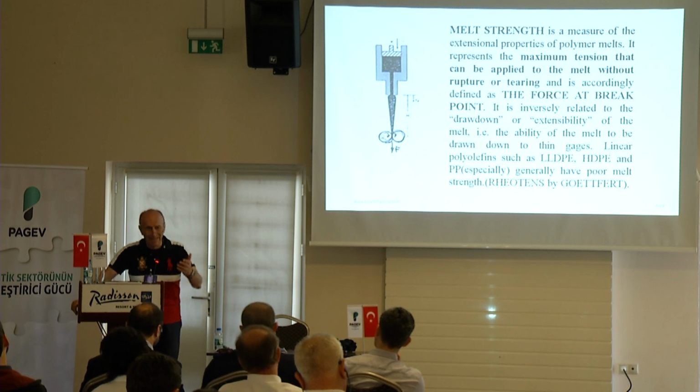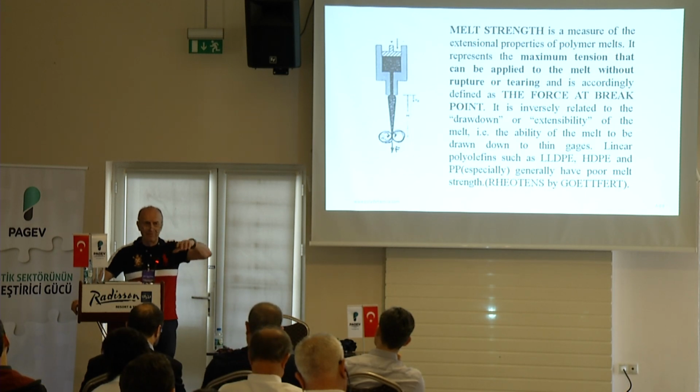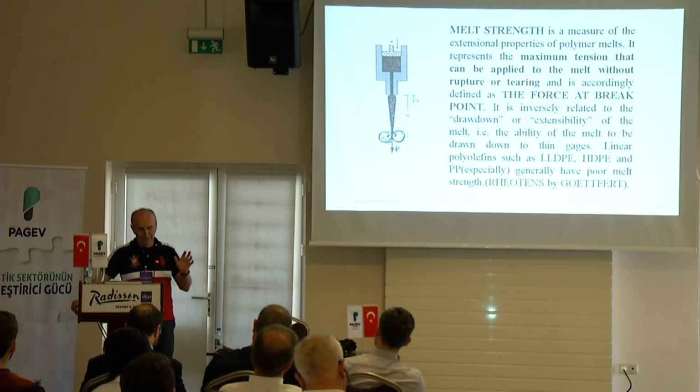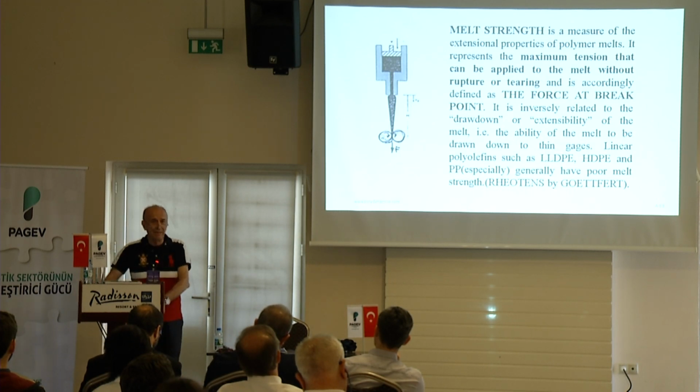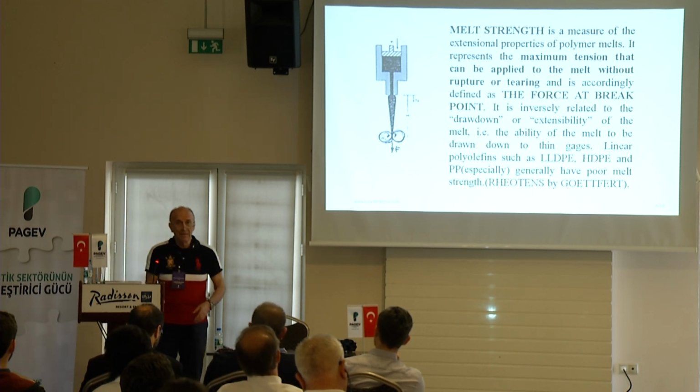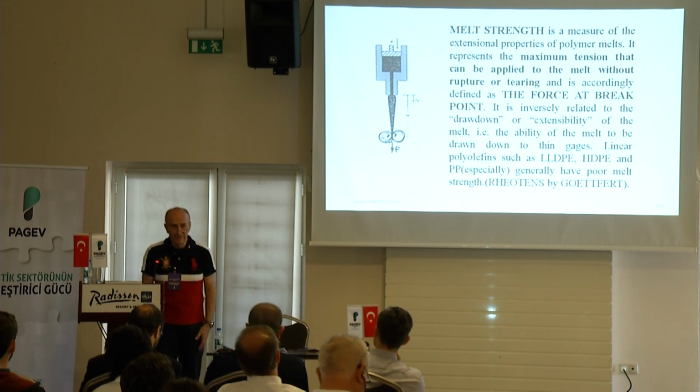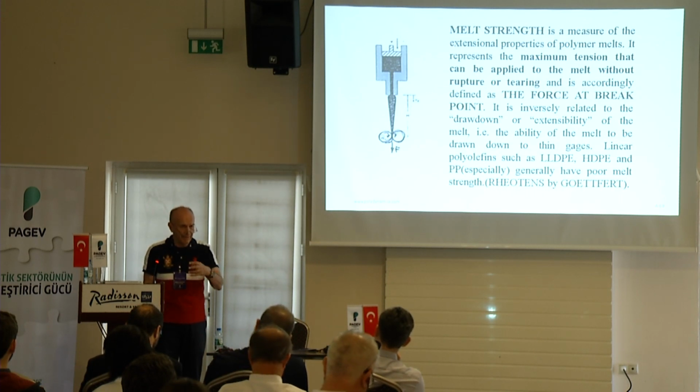So it's like the melt index equivalent. Melt index for shear, melt strength for elongational. You can relate it that way. And so this is an important measure in some processes. If you are dealing with films, with fibers, also if you're dealing with pipe production and so forth. Like, it's important in thermoforming.